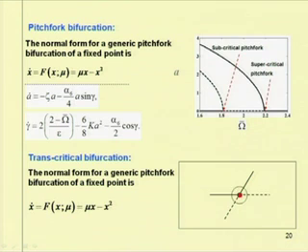So, the subcritical bifurcation point is a danger or catastrophic failure point. At this point, if one increases this control parameter omega bar, the system will have a tendency to jump up. Here it will jump up to the upper stable branch. In the case of this nonlinear system, one can observe that at a particular control parameter, one has multiple types of response, or multiple solutions, present in the system.